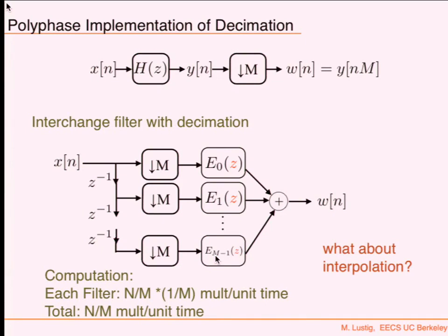Okay. What do you do when you do interpolation? You want to filter at the low rate and then upsample. Okay? So you'll get a similar situation where you can come up with a decomposition that would filter, upsample, delay, and add. Okay? That would be the result. Then that doesn't have to be a result of an upsampling, of an expander, right? If I delay and add things, then I would have things in between.